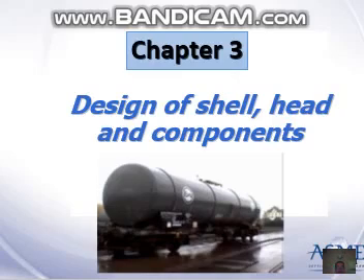The shell is the primary component that contains the pressure. Pressure vessel shells are welded together to form a structure that has a common rotational axis. Most pressure vessel shells are cylindrical, spherical, or conical in shape. Horizontal drums have cylindrical shells and are fabricated in a wide range of diameters and lengths.